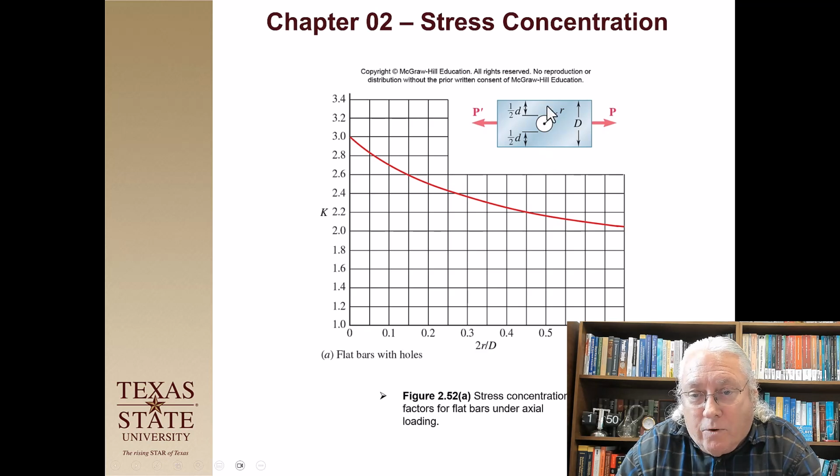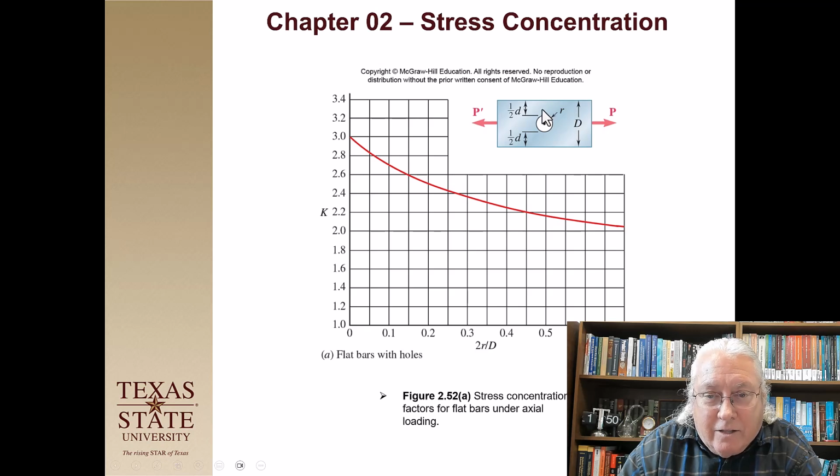So you can imagine this force has got to get to the ground, right? We know that the load is going to travel the path of greatest stiffness, greatest resistance. And so this load is going to start off being evenly distributed on this right side here, and it's going to be evenly distributed until it gets closer to this hole. And the load is going to magically know that it can't go through the hole because there's zero stiffness at the hole. We're going to turn the corner and then it's going to go up here. It's like water flowing down a river. It's going to flow nice and smooth here, but when it gets close to this hole, it's going to rush around. It's going to cause that stress concentration factor. And then it's going to settle back out to this other shape.